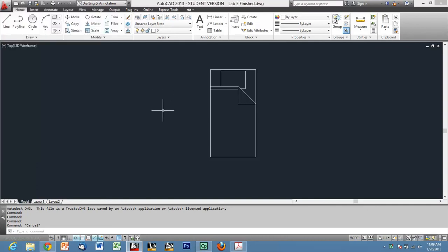And then when they go back into another drawing, they would insert the drawing as a block. But the problem with that is that you can get what's called a circular reference in AutoCAD, where it looks at itself for something and it basically goes in circles over and over, and it freaks out, and it'll tell you you have a circular reference down here, and it will not insert the block.